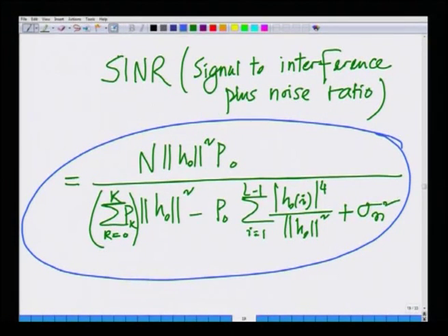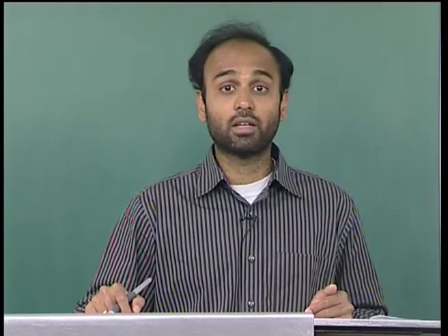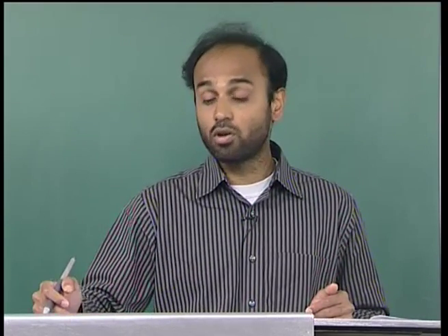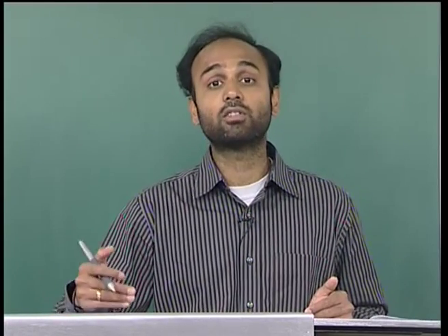And let me point out one final thing. If you want to increase the SINR by pumping more power P naught into the desired user, that can have repercussions, because as the desired power increases in the numerator, look at this, in the denominator also there is a P0, because the rest of the paths are interfering with the desired path. So, that increases both signal power and interference power. This is not something that we have seen before. So, this is something that is strange, and this is something that is the cornerstone in wireless communications, especially CDMA, because of the rich interference. When you increase the power, the interference also increases.